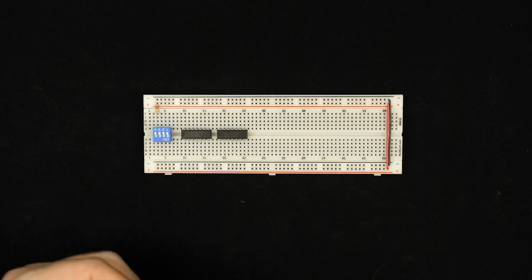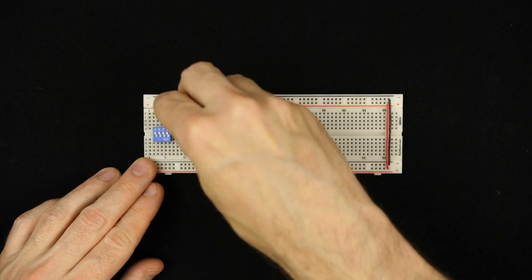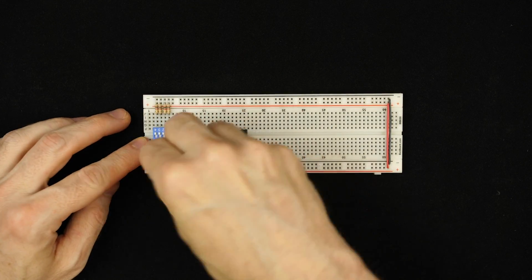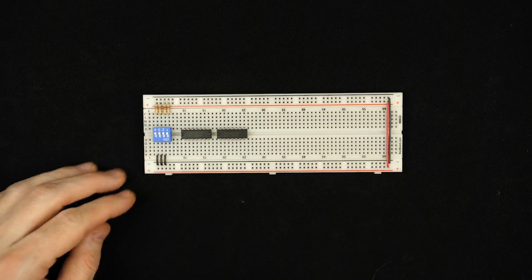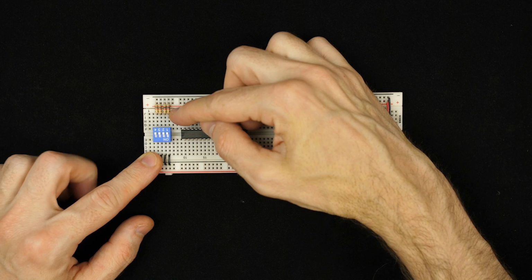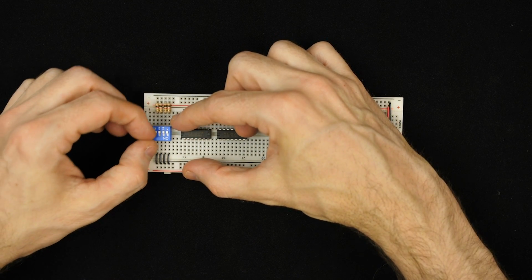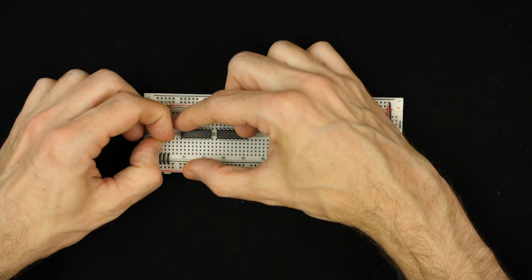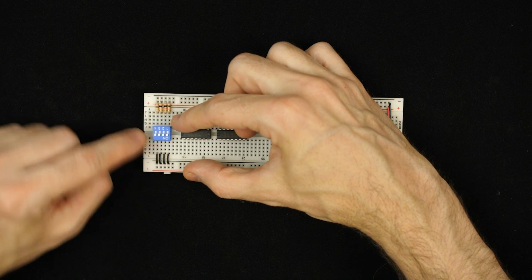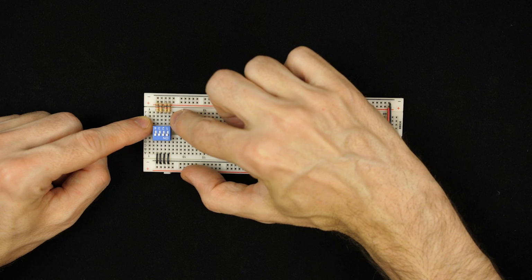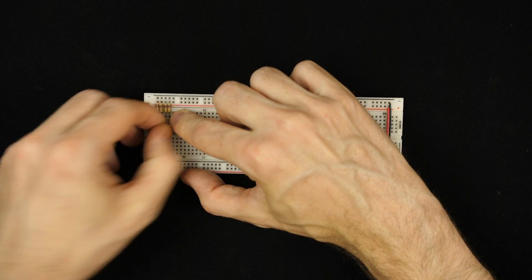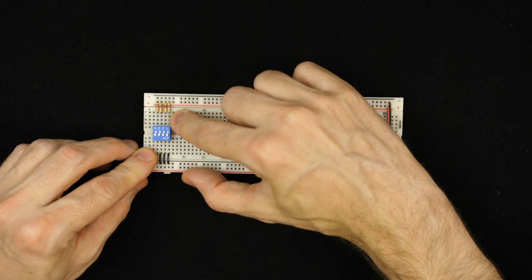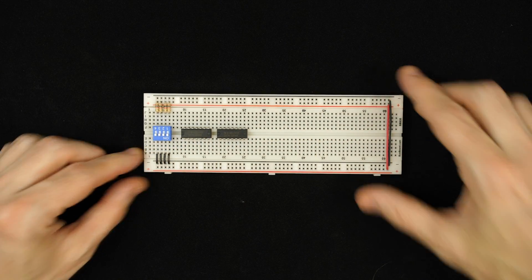And I'll have one side of the dip switches tied high through these 1K resistors, and then the other side of each switch I'll just tie directly to ground. That way on this side we'll have 5 volts through the resistor, but then when we turn the switch on, which is actually pushing it down, it'll connect through to the ground and bring this top side here to 0 volts. So we'll either be at 5 volts if the switch is up or 0 volts if it's down. And so that's how we can set our 4 bits.